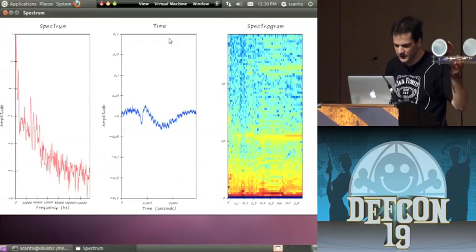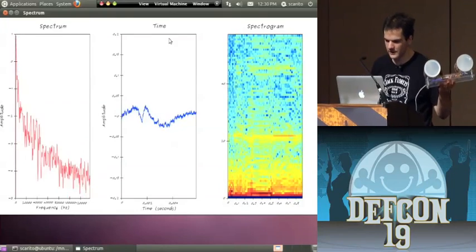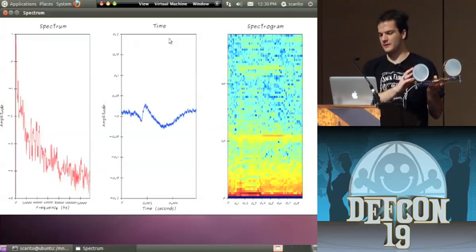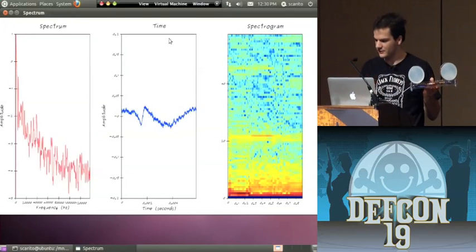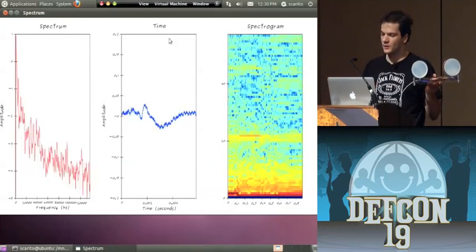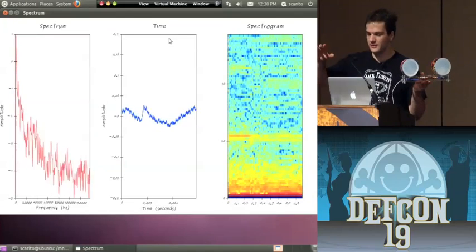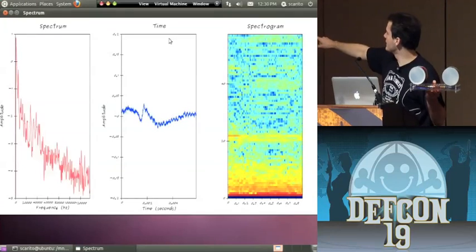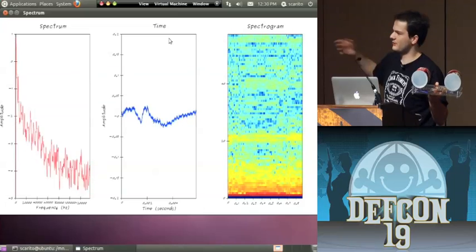And the other thing, which I haven't actually seen yet, which I'm a little surprised by, is that this thing operates in the Wi-Fi band. And there's a lot of noise. I'm not exactly sure why that's happening. That wasn't happening before. But what you do see occasionally is these pulses towards the top end of that. And that's actually Wi-Fi signal bursts from the thing transmitting.